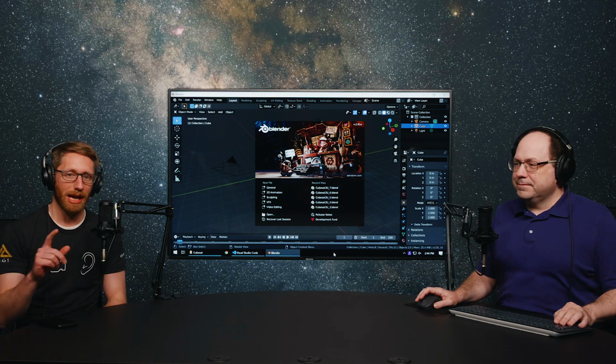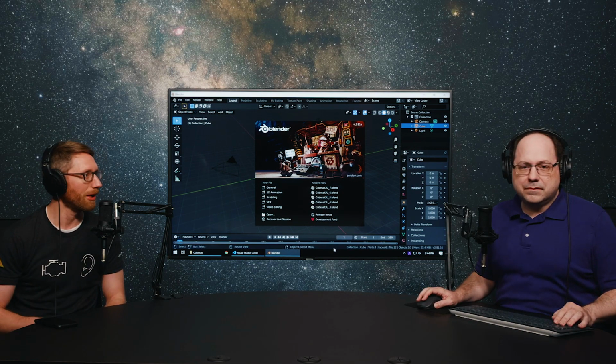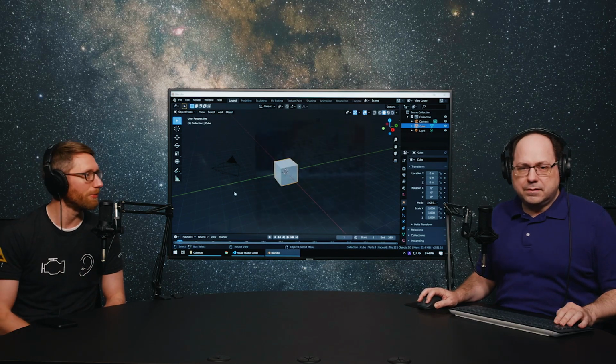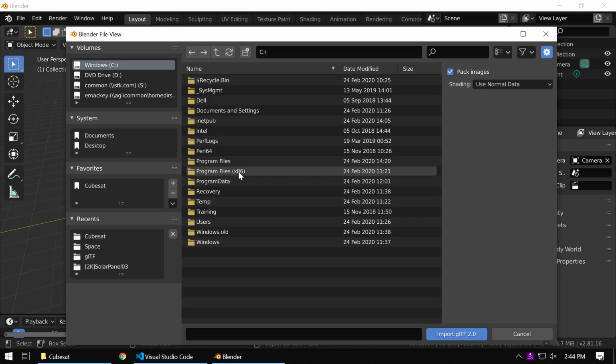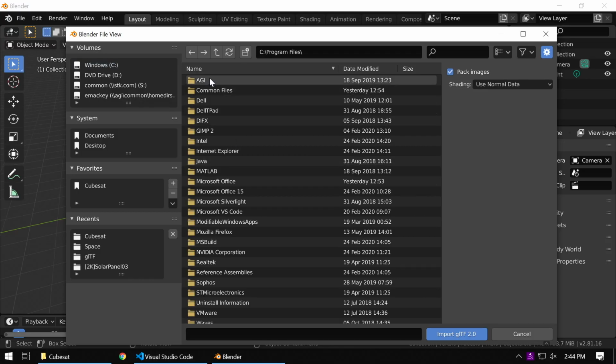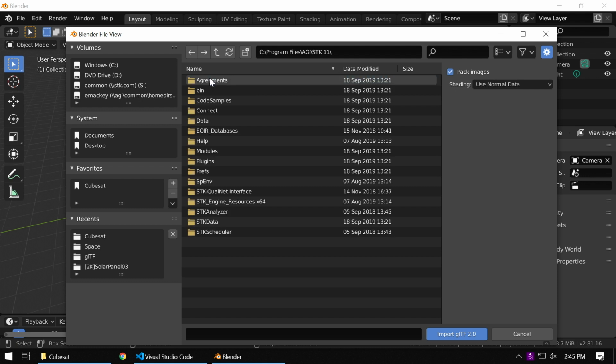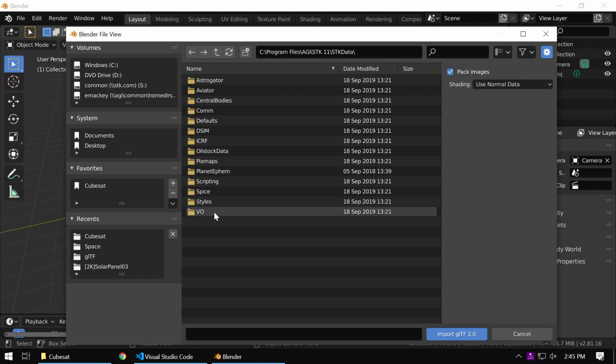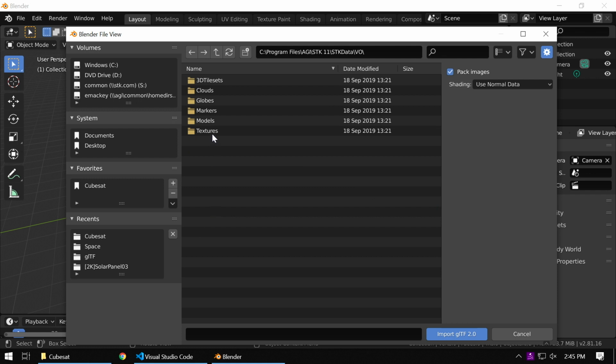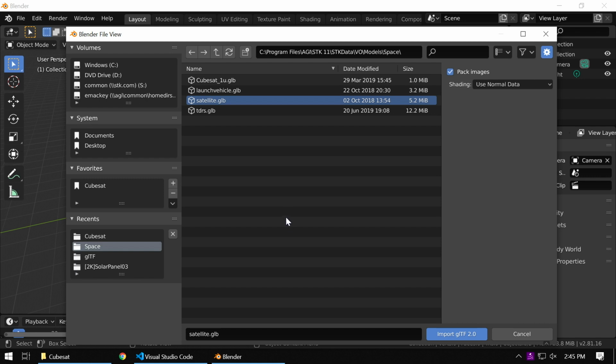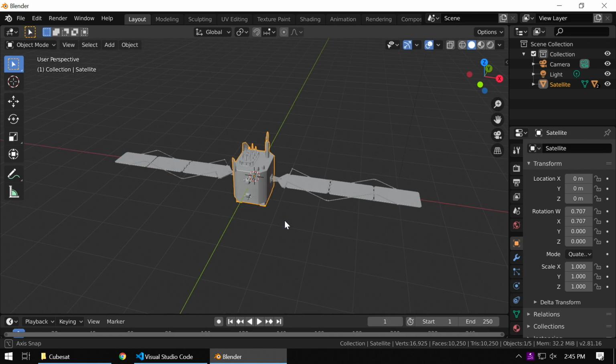That's right. So actually, Ed, while I lead us in with what ambient occlusion is, can you pull up an interesting model that might show us? Sure. So ambient occlusion is this detailing that you can put on your model, a way of toning down the light contribution. Think of it as self-shadowing of the ambient light that's coming onto the model. If you had a tube, you would expect the inside of that tube to be darker because the ambient light is not reaching those inner parts of the tube.